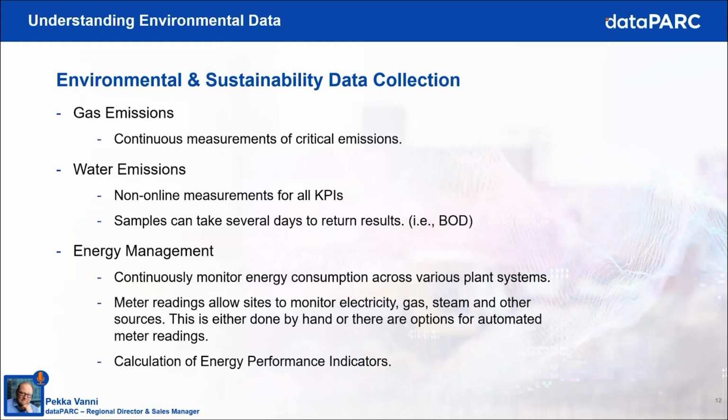If you are implementing an ISO 50001 compliant energy management system, you need to collect data related to thermal energy consumption, like pressure, temperature, and quantity of steam, and then calculate energy content. For measuring electricity, data is collected from electric meters, and in some countries, authorities require the capability to observe significant energy units in great detail.